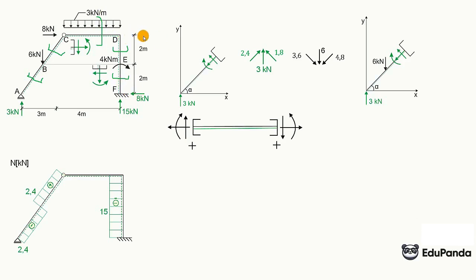If we move it here parallelly, which is what we have to do, and also it has a direction opposite to the positive indicated here. So we have a constant value of minus 8, because there are no other horizontal forces on this rod. We have drawn the normal force graph. Next, we will start drawing the shear force graph.